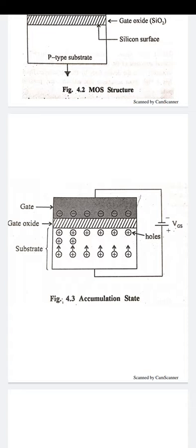But no current flows between the drain and source, because we have applied a negative voltage to the gate terminal. In the p-type substrate, where the majority carriers are holes, we have positive charge, and towards the negative voltage of the gate it is attracted between the source and drain. That is the accumulation of charge between the source and drain underneath the gate. But even with the presence of these charges, when we have not applied the drain to source voltage and only the VGS voltage, no current exists between the drain and source of this channel.